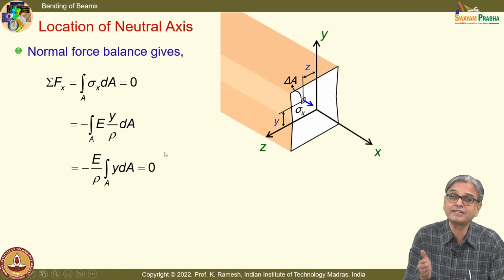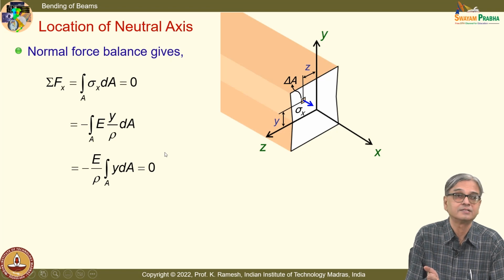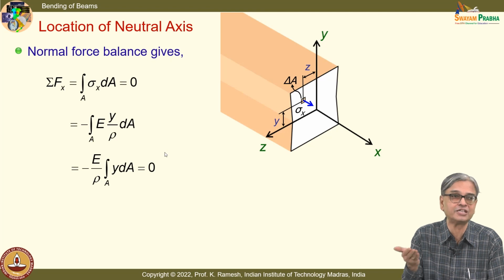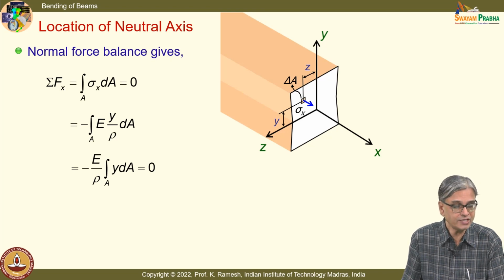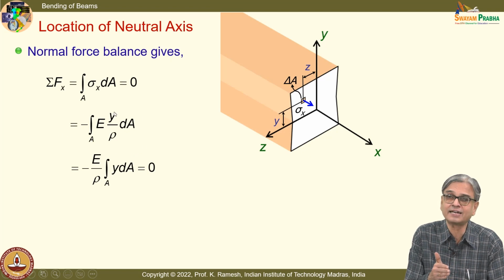Suppose I have a material which is non-linear. When the material is linear, I have only one E. When the material is non-linear, E keeps changing. So what is fundamental here is that this equation is more fundamental for you to extend whatever understanding you have developed to other problems than isotropic material of constant properties across the complete beam.